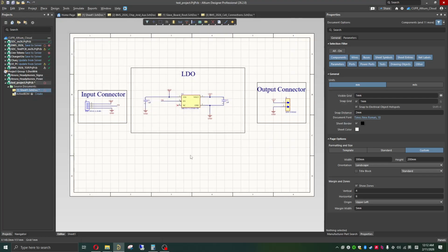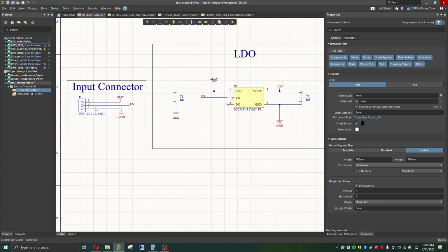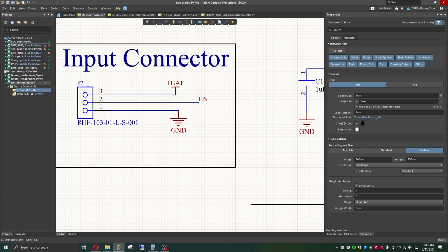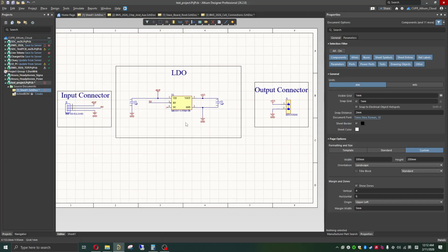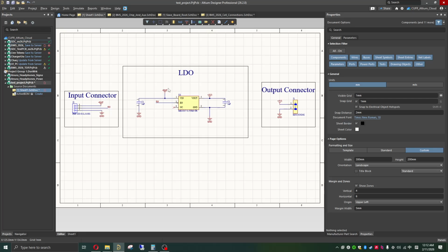Wonderful. Now I can close, and we can see that our circuit looks pretty clean. One thing that you'll note, and you might run into this when you're doing your schematic, is that you might have red squiggly lines over certain components. That usually indicates that there's an error in either the way that you've defined your component or in the way that you're trying to use the specific node that you're working with. Usually when you highlight on a component, it'll tell you what that error is. Here it just tells me that it's a power object, what the net name is, and stuff. But if you run into any obscure issues, check some of the forums first, but of course, I'm happy to answer any questions as well.